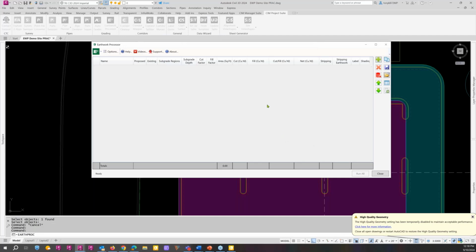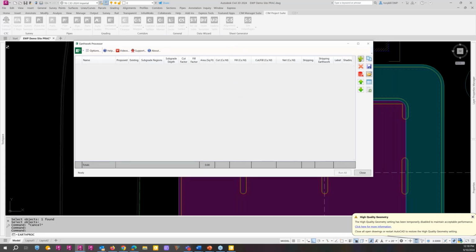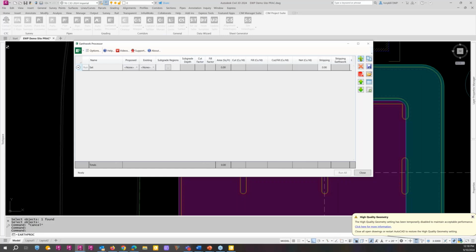So I'm going to say OK here to save those options. Then over here, here's how we create our sets. Why didn't that change? Oh, that's for my tables, not for this header. So that was for my tables. I set that in AutoCAD. So if I hit the plus right here, this is how we start to build a new set.